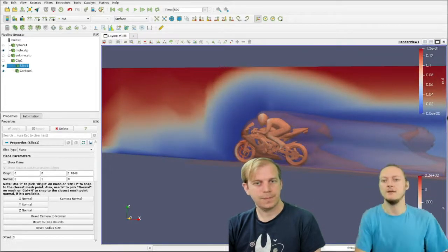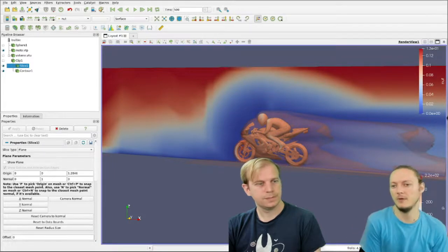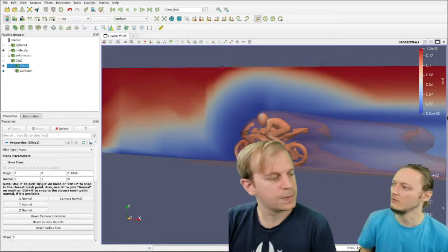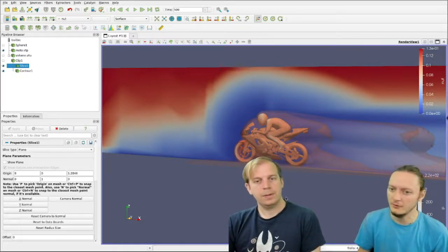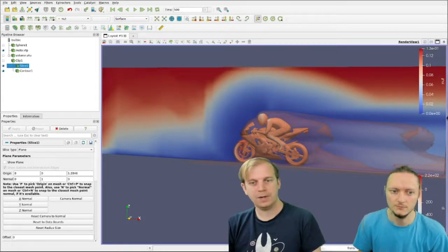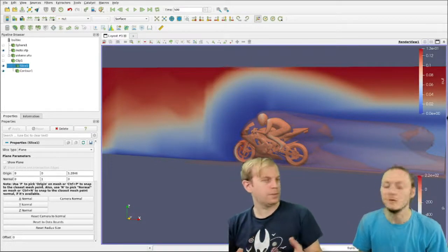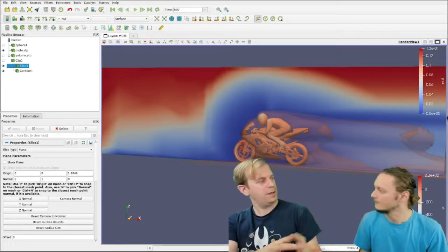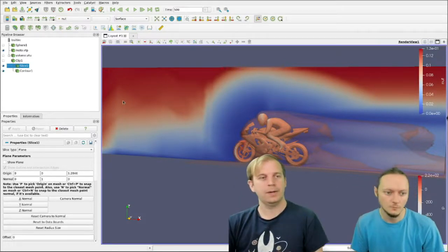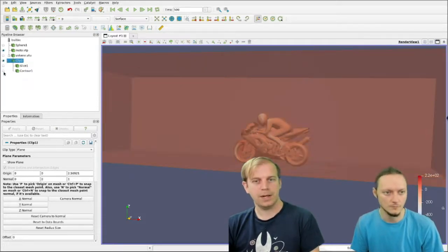I see. And when working with this kind of CFD data, maybe we can also be interested in some glyphs or streamlines. Can you give us an example of this kind of processing? Sure. So let's start with streamlines. For the streamlines, you want to do the streamlines on the volume. You have to put some seeds into it, and the streamlines will just compute the movement of the particles. So to do that, let's select our clip volume again. I will hide everything